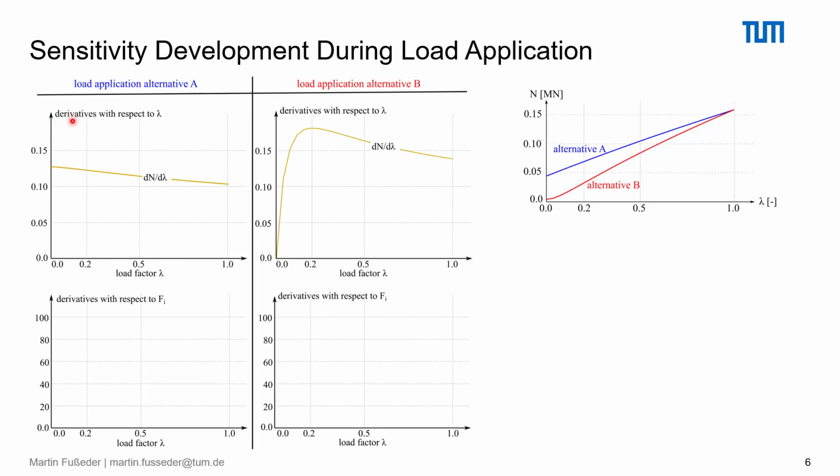These diagrams show us the development of the derivatives during load application. The first derivative we would like to observe is the derivative with respect to the load factor lambda, which means these are the derivatives of these two curves here. Clearly we can see that through the stepwise load application of the dead load, some artificial nonlinearity is introduced.